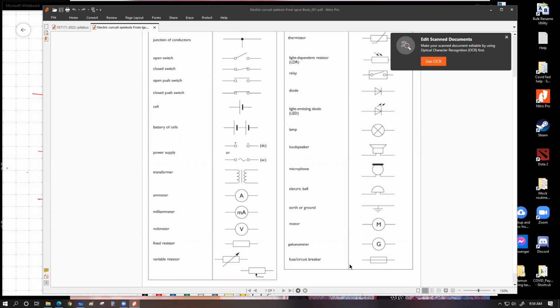But the fixed resistor is actually a significantly theoretical idea because physically speaking, any object's resistance is always dependent on its temperature. There are two types of things which are called PTC or NTC. PTCs are called positive temperature coefficient and NTCs are called negative temperature coefficient. PTCs are those which have a rise in their resistance with temperature increase. And NTCs have a lowering of their resistance as temperature increases.